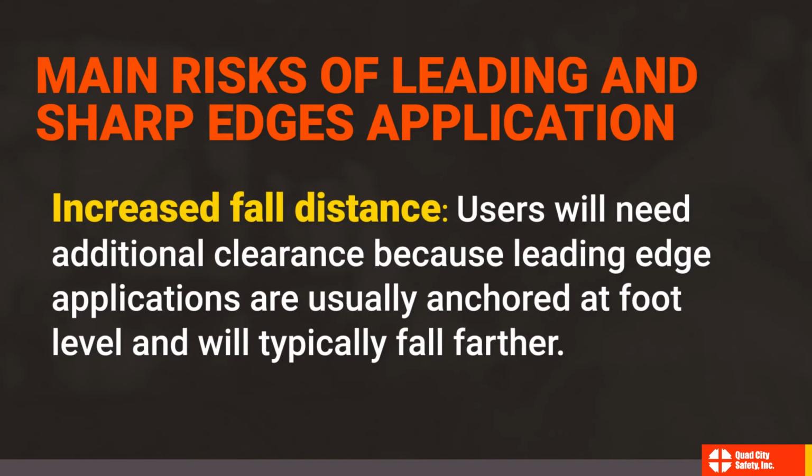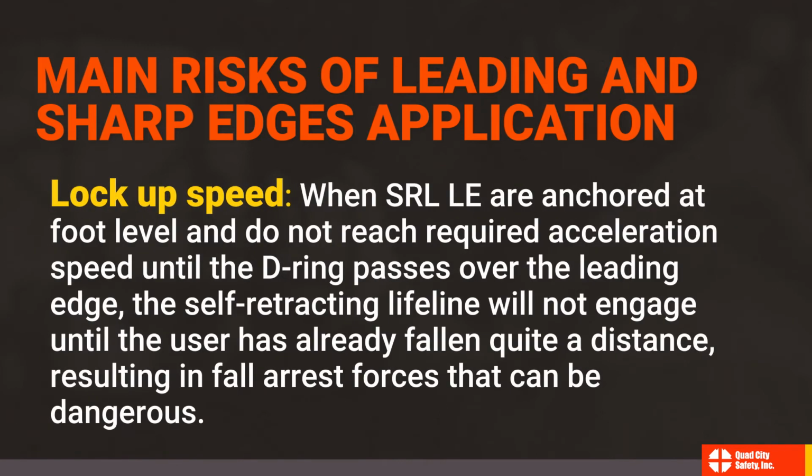Increased fall distance. Users will need additional clearance because leading edge applications are usually anchored at foot level and will typically fall farther. Lockup speed. When self-retracting lifelines with leading edge are anchored at foot level and don't reach required acceleration speed until the D-ring passes over the leading edge, the self-retracting lifeline will not engage until the user has already fallen quite a distance, resulting in fall arrest forces that can be dangerous.